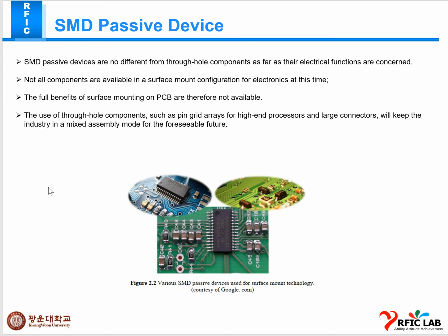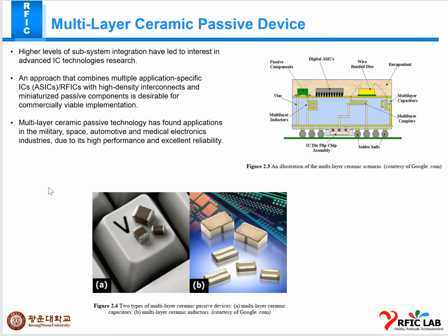Not all components are available in surface mount configuration at this time, and the use of through hole components such as pin grid array for high end processors and large connectors will keep the industry in mixed assembly mode for the foreseeable future.